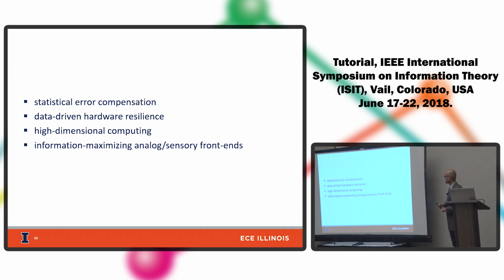So there are 4 techniques, 4 topics that I want to go over to give you an illustration of the sort of design principles and design techniques we have come up with already to handle circuit level stochasticity in a very unconventional way. By unconventional, I mean not relying on traditional fault tolerance computing techniques. One mainstream technique in fault tolerance is replication. You just replicate the compute units and do a majority vote, right? That reminds you of repetition coding. Here, these are totally different compared to those conventional approaches.